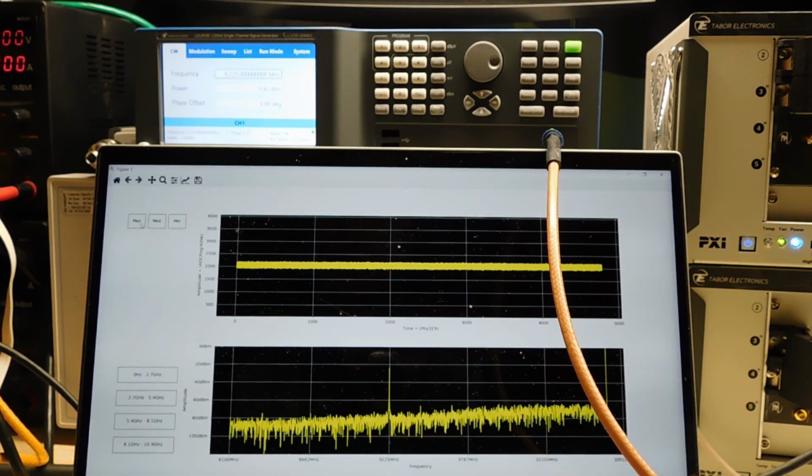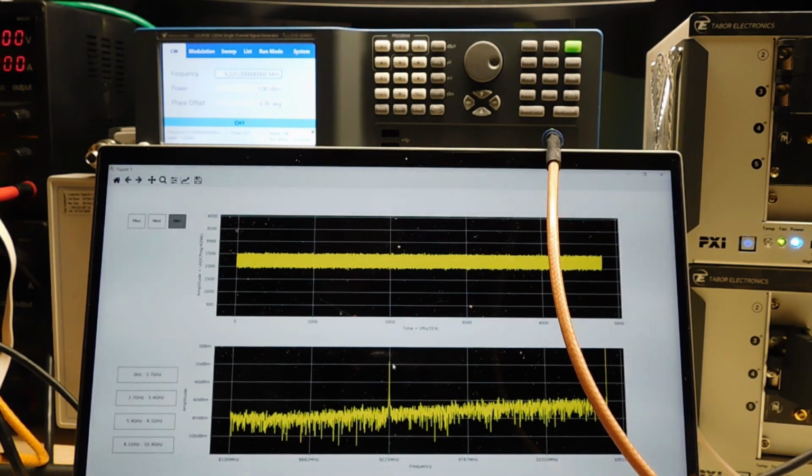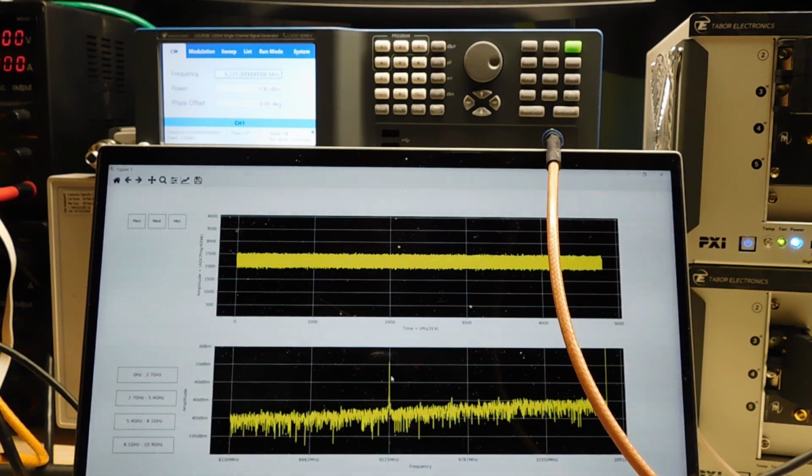So I originally had the range set to max on our analog to digital converters. I'll set it to minimum. You can see that's given us an improvement of the gain here. So we're at about minus 18 dBm, down from the 0 dBm that we had originally, but we're up at 9.225 gigahertz. And finally, let me take it all the way up to